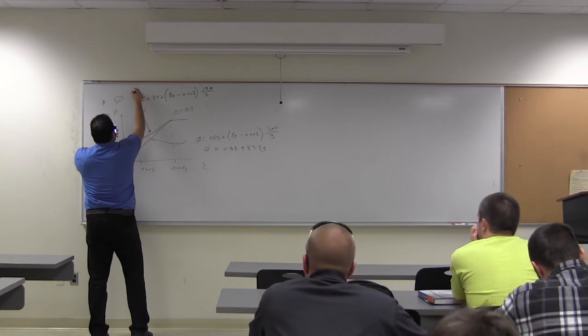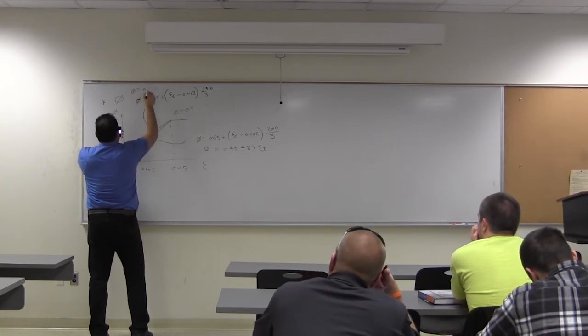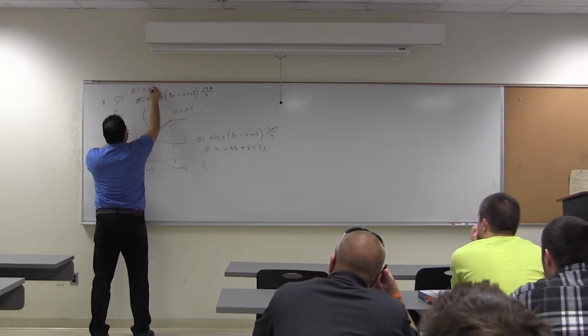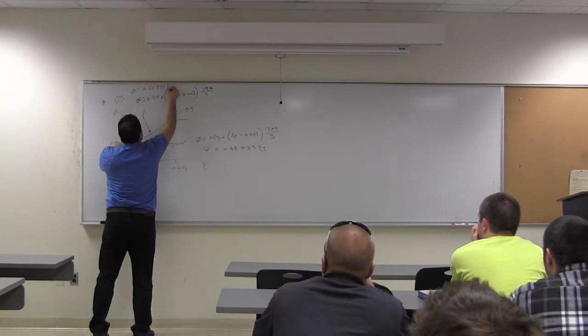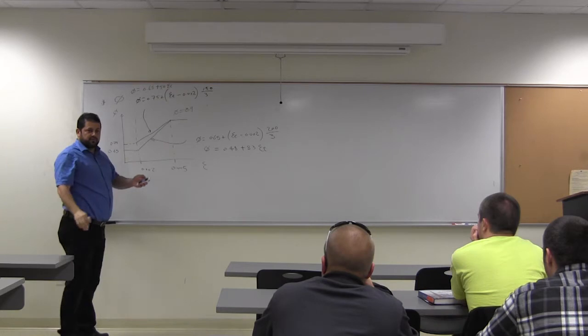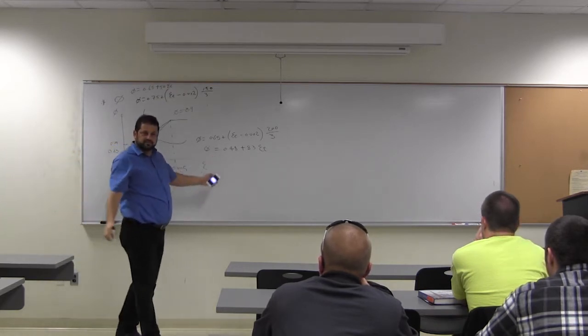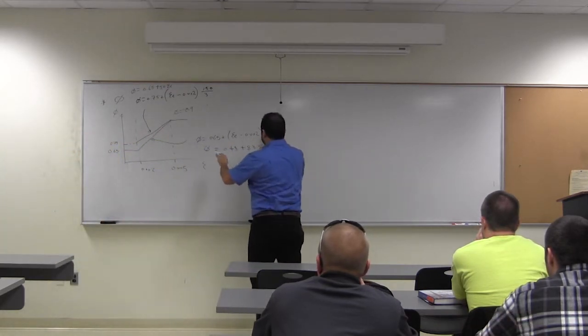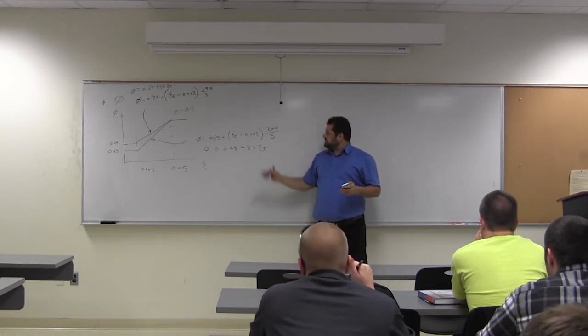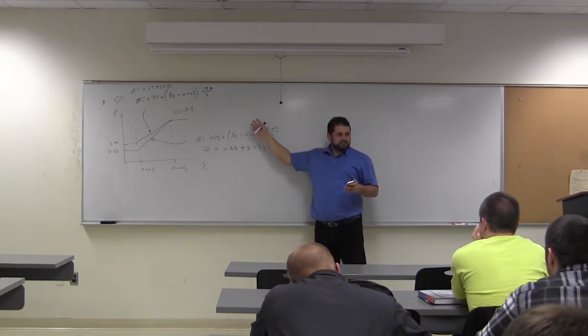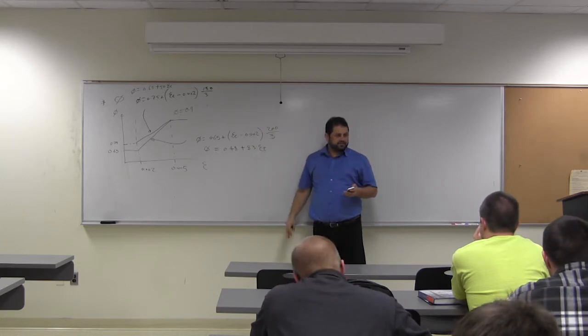And for spiral, Phi equals 0.65 plus 50 epsilon t. You can check, they should give you the same answer. You just rearrange or reorganize the subtraction. That's the strength reduction factor.